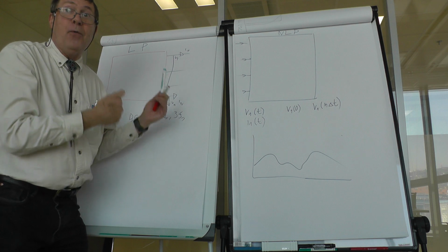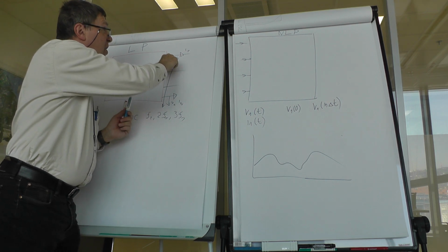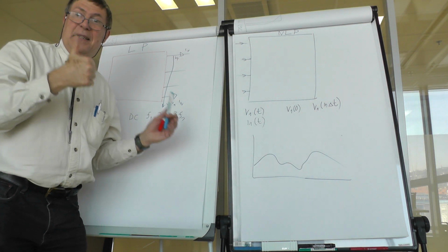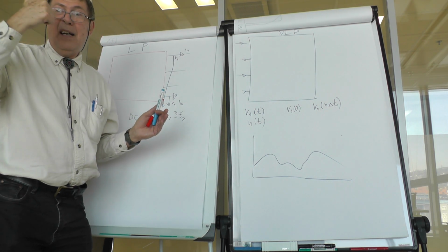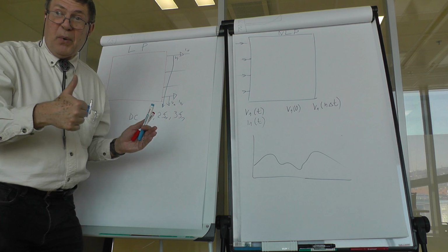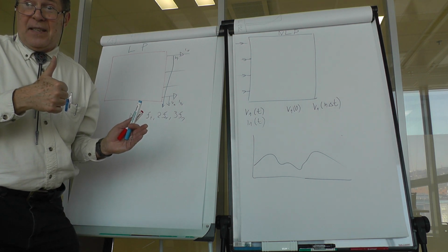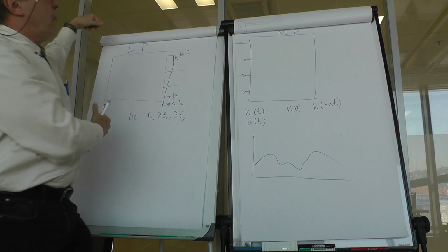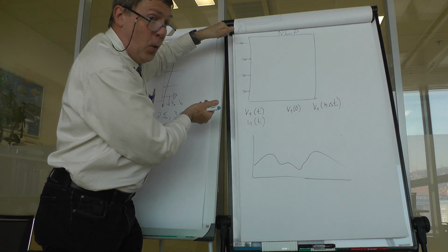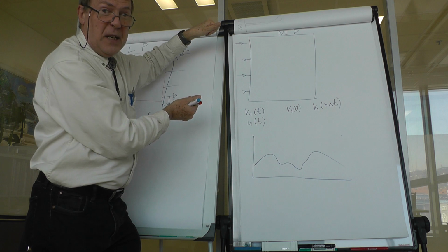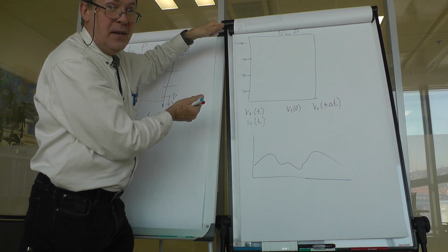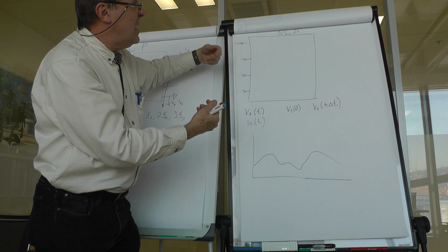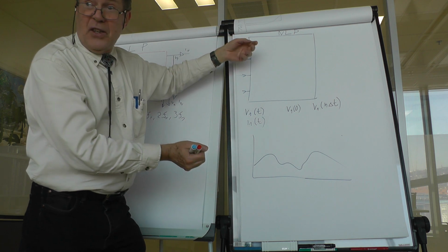Still, I will get for each voltage, for example V1, frequency components, that is the DC part, frequency component magnitudes, and phase shifts. Once I have this, I can feed it forward to the inverse Fourier transform and get time samples of the voltage.